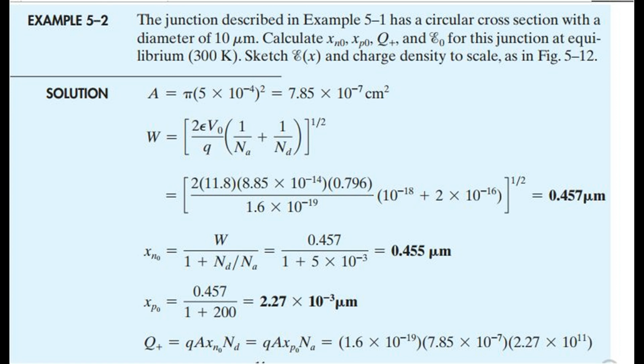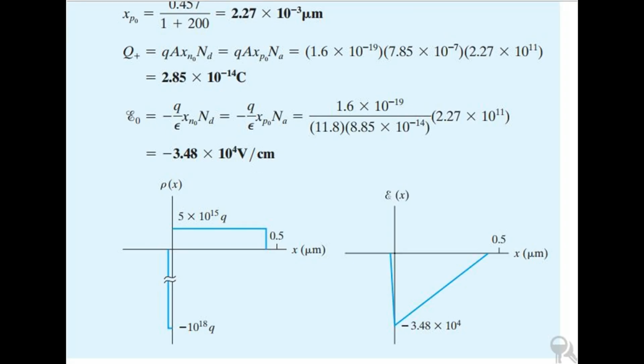One useful feature of a p-n junction is that current flows quite freely in the p to n direction when the p region has a positive external voltage bias relative to n, forward bias and forward current, whereas virtually no current flows when p is made negative relative to n, reverse bias and reverse current. This asymmetry of the current flow makes the p-n junction diode very useful as a rectifier.